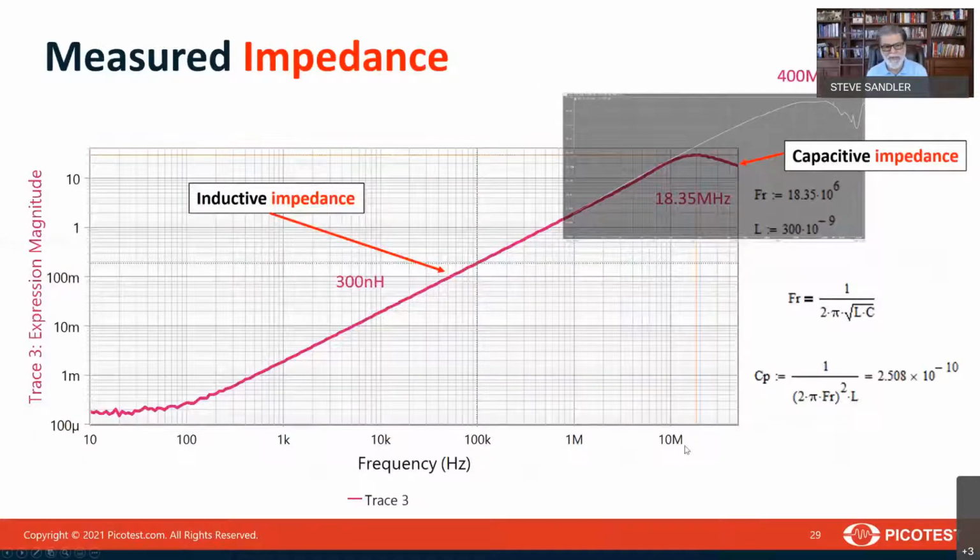We actually measured that inductance, and it's 300 nanohenries, right about where it's supposed to be. We can also see its resonant frequency here at 18.3 megahertz, and if you calculate the capacitance, that says that there's 250 picofarads of parallel capacitance.